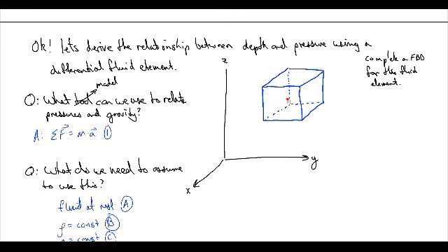I like to draw our forces in red. So we're going to draw the one body force going down, because we have mass times gravity acting on our system. And that is going to be rho times g, but we need a mass times a volume.